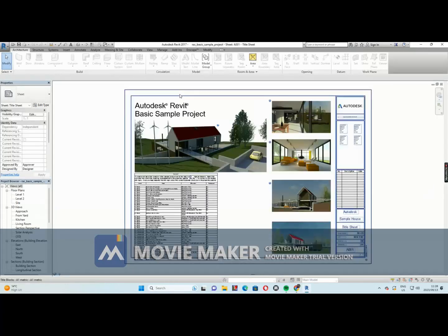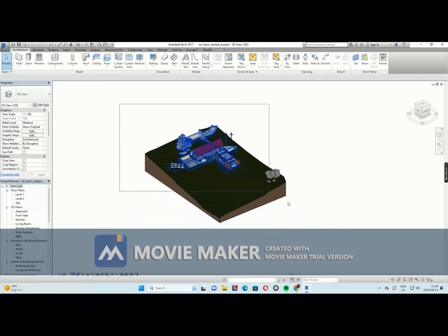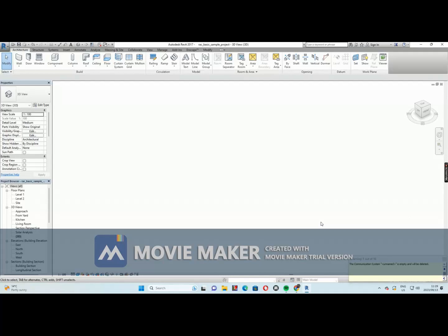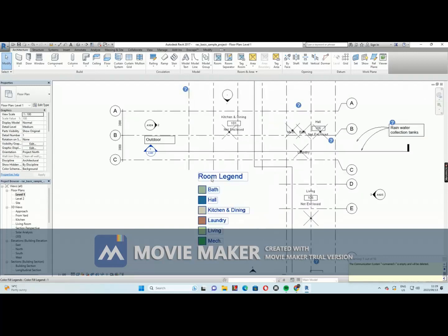So what we do now is we just delete everything here. We go to 3D here, you highlight everything, you click delete, it's gone. Then you go to your levels. There's something which is remaining here. These are not 3Ds, that's why they are still here. Delete. You don't have to delete this.